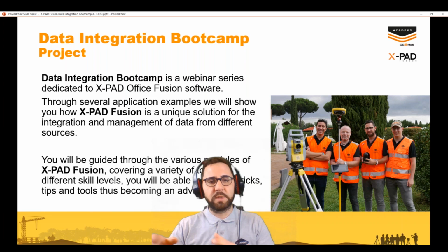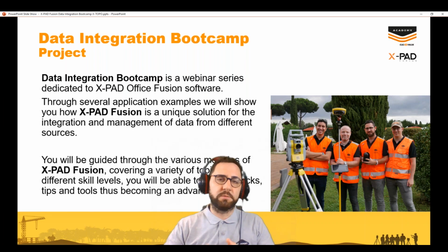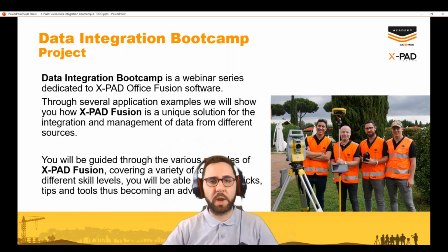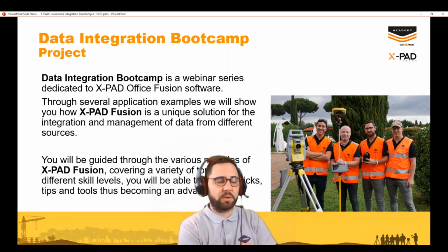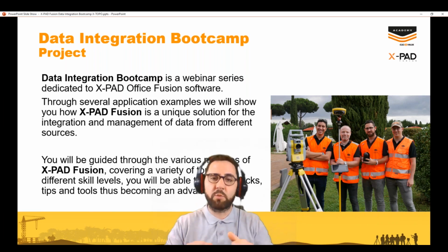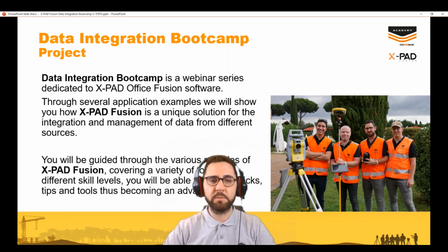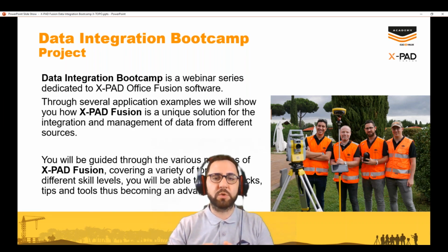And laser scanning data using the BLK 360, plus we also used the DJI drone to measure and collect data for aerial photogrammetry and a reflex camera for the terrestrial photogrammetry. Then we collected all this information together and imported it into the same platform, X-TOPO Office Fusion, to create a big data set that is also available on our website, the X-TOPO 365 platform. And then we use all this data in the same software, X-TOPO Fusion.